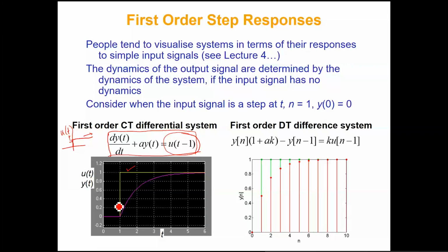Right? And if you give this input, we can just see what sort of output we get. What will be y of t? So this is your x of t, and this is your y of t. So we can give different x of t and just see the plot of how y of t will look like. So these types of things we can do in MATLAB using Simulink.